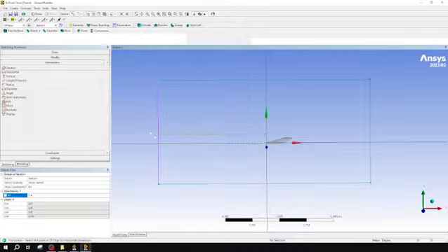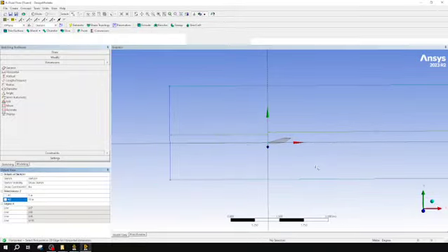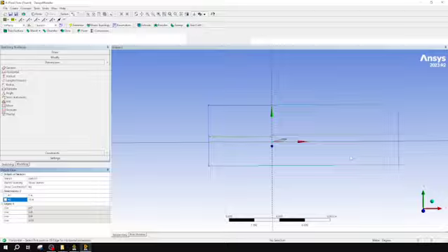Now that I got the space in front, I'm going to go for the space behind. So again, I still have horizontal, and I'm going to control click for my second line to get this second distance. This is the one I'm going to do 10 meters. 10, my bad. What I'm noticing is if I put an M in after my measurement, it doesn't actually save it, so I have to do it afterwards.